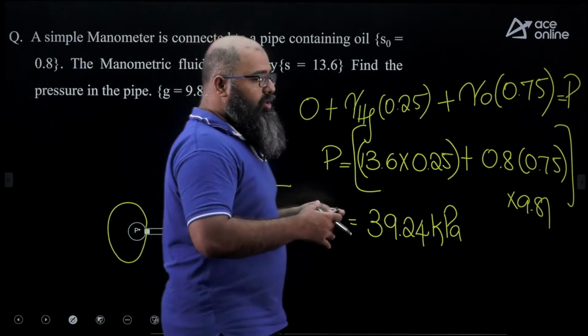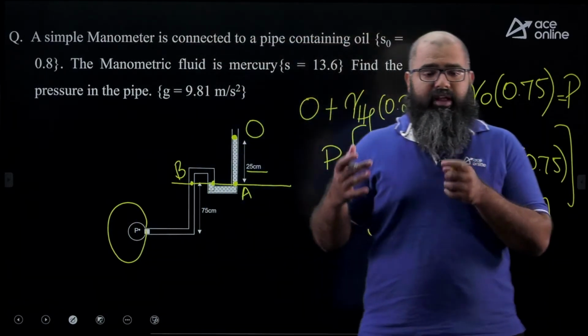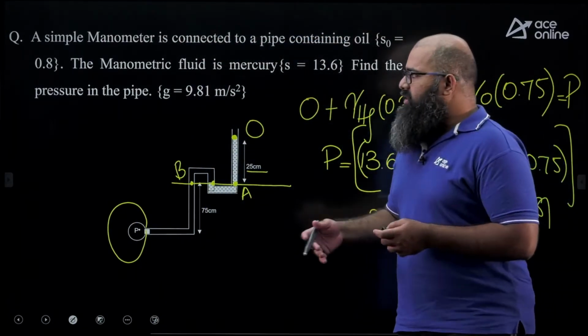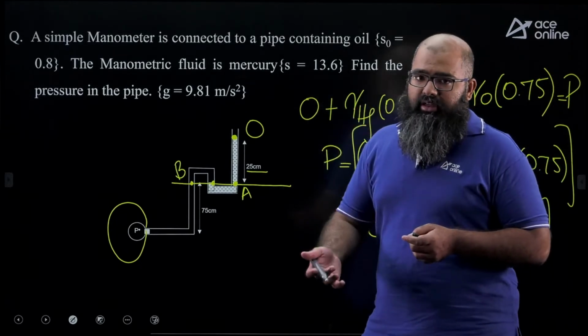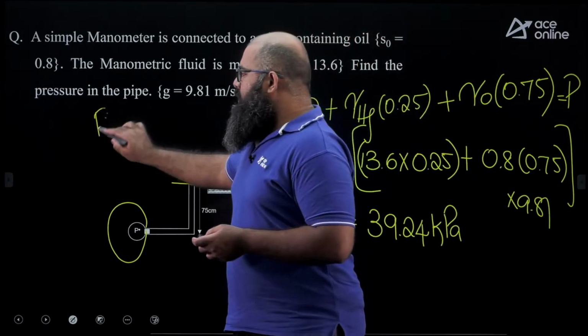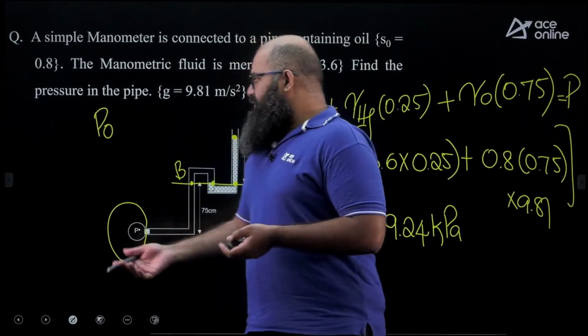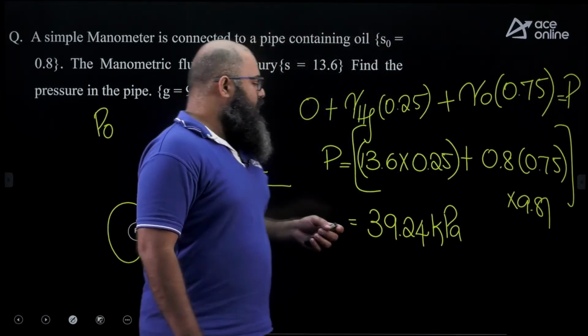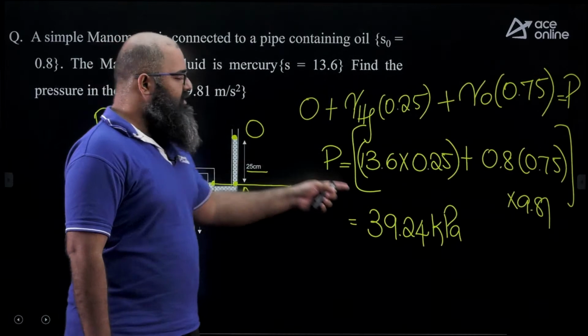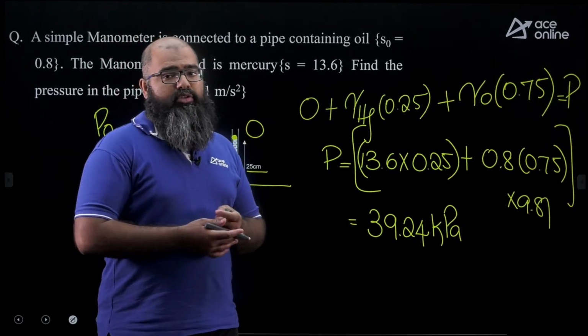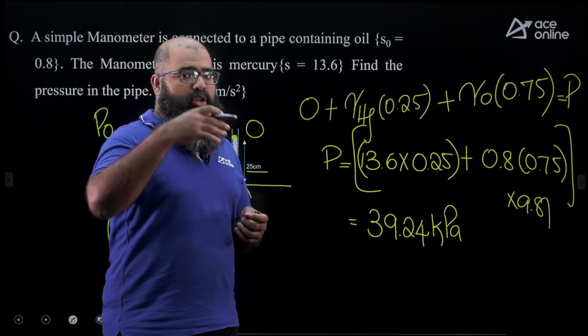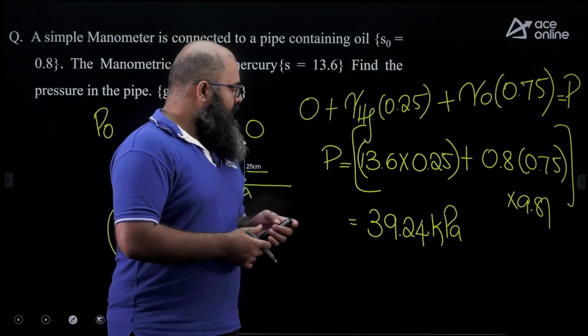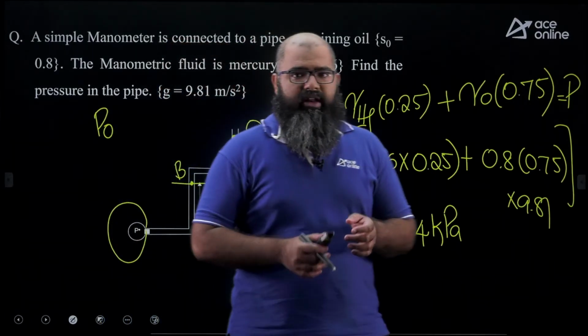Now I cannot assure you what was asked in examination, since this is what we have got from students. If the question was regarding the value of absolute pressure, they should have given you the value of local atmospheric pressure. And if so, we can say the value of absolute pressure is equal to how much? It is equal to P naught plus this gauge pressure. Again, the units over here are important. You have to check what units they were asked in. Fine. These two questions are the questions we have received in FM1.